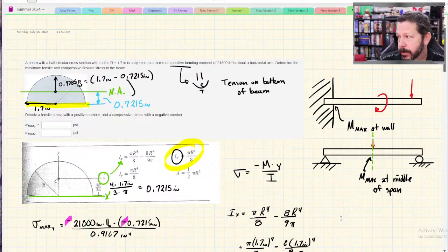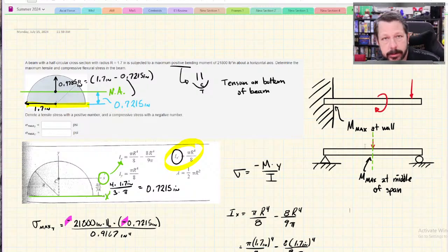I'm relatively certain, maybe, I don't know, 80% certain, that one of these, either a simply supported beam with symmetric loading or a cantilever beam, will be on the exam too, where you have to find something like maximum stress, and you'll be able to do that faster if you remember that you don't need to draw the shear and bending diagram, maximum moment is at the wall.